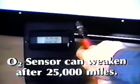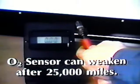Just to show you what a weak, faulty sensor reading would look like, we'll try the test with this one here. Keep in mind that O2 sensors can start to get weak after as few as 25,000 miles. It's important to make this test because a sluggish sensor can cause problems. When we heat this faulty sensor, the meter reads 0.6 of a volt in the first 15 seconds. But after the full 60 seconds, it has not risen very much. What's more, when we remove the heat source, the voltage slowly drops.